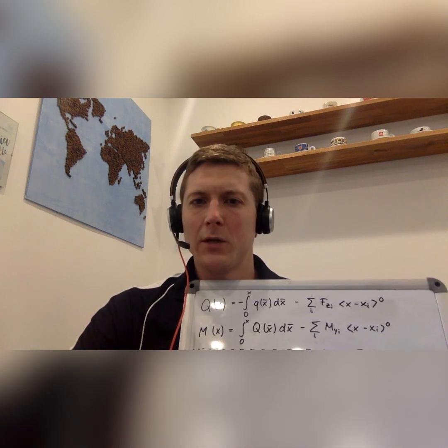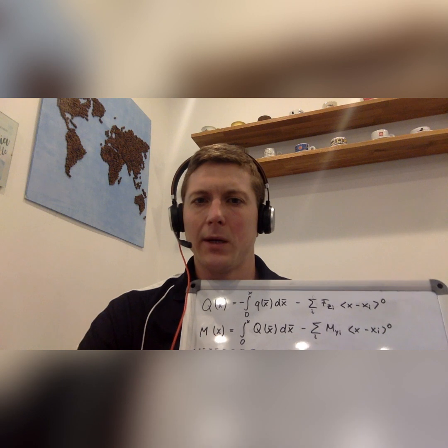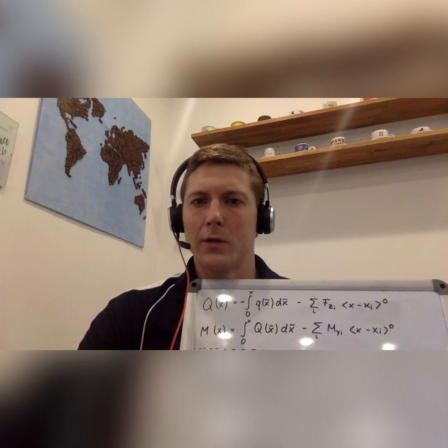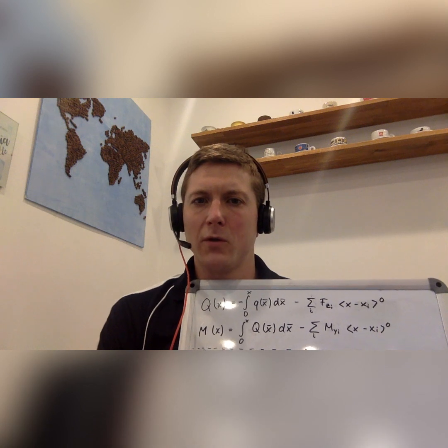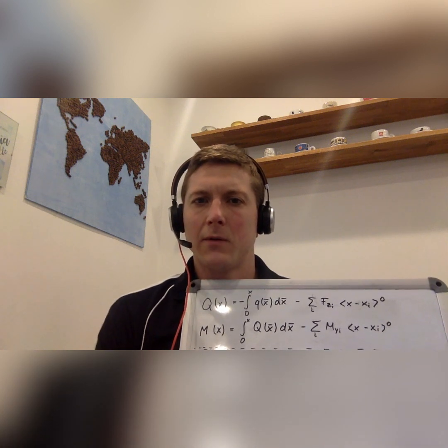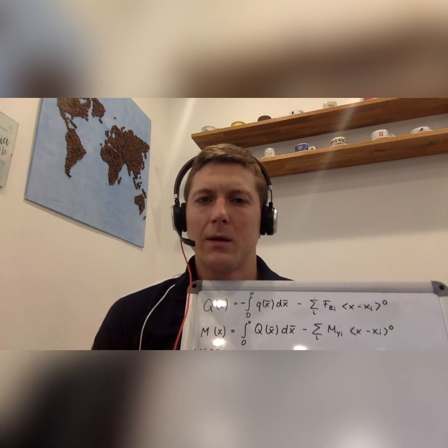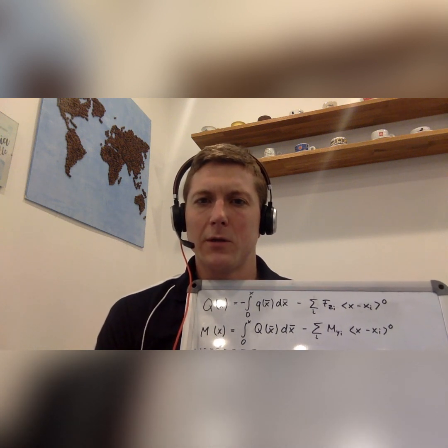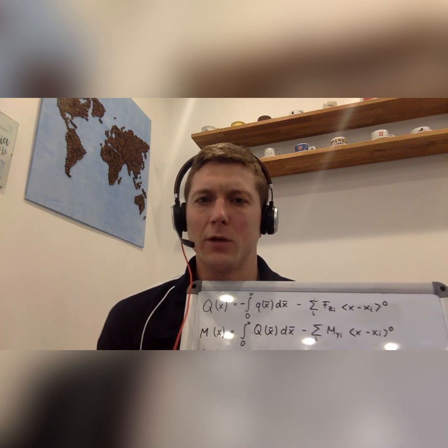So 3 equations for your beam, and it might be the case that you have more than 3 unknowns out of your free body diagram. For statics, so for the first half of the course, it would not be possible for you to solve these equations, but for elastostatics, mechanics of materials, we get additional equations because there is a relation between the bending moment and the deformation of the beam.